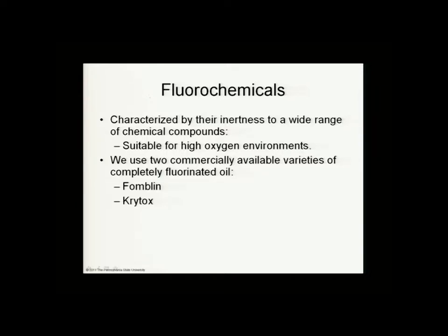Fluorochemicals are a type of these synthetic oils we're discussing. These are characterized by their inertness to a wide variety of chemical compounds. That is, inert means they don't react with things. So these fluorochemicals, which are a type of synthetic oil, can be very suitable for high oxygen environments. And there are two prominent commercial varieties of these completely fluorinated oils. One is called Fomblin, and the other is called Krytox.